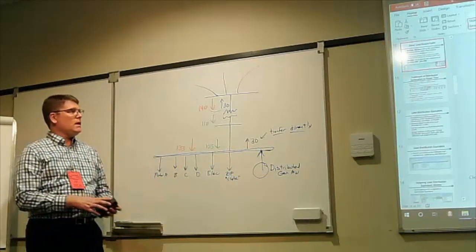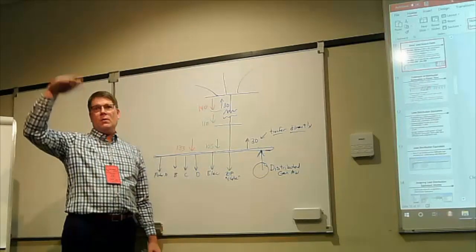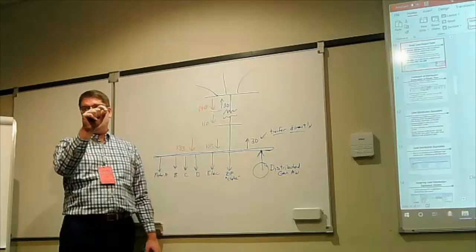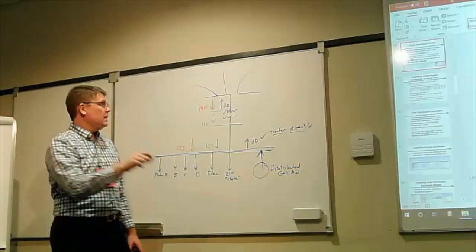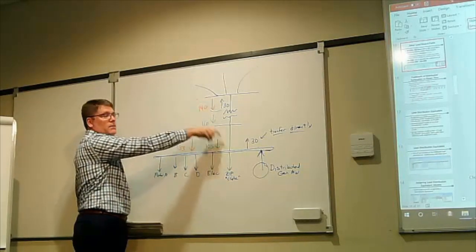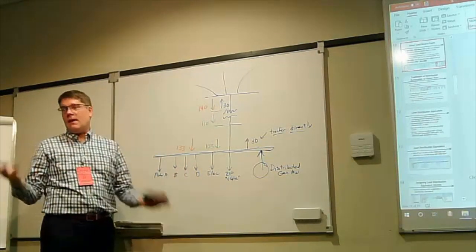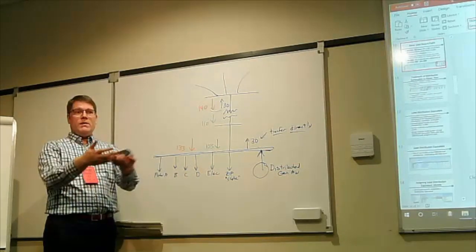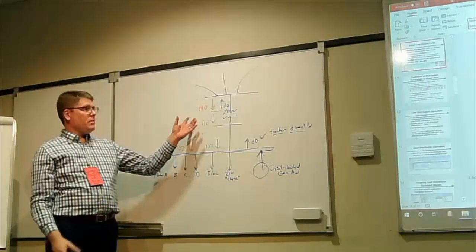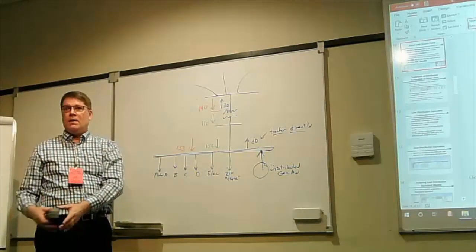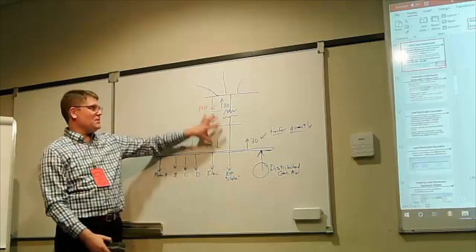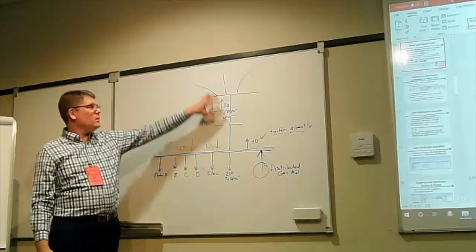I'll comment when you're looking at reporting. If I do a plot of what is the load megawatt at a particular load in transient stability, I get this number. So it's essentially including the feeder losses. Because what you're asking, at least I assume, is what is the transmission system seeing as the load. Otherwise, the moment you switch to the composite load model, the load in your system drops 5% because the losses just went up, and you really want the reporting.